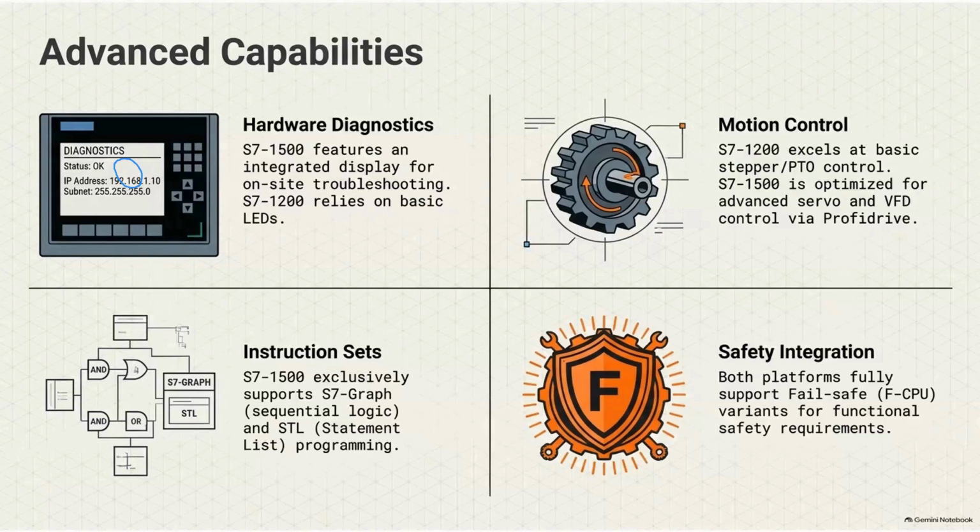So what they do is they look for the n number of times it has opened for n number of seconds, and it assumes, so if the door is kept in open condition for about 10 seconds, the temperature drop is this 30 degrees or whatever. So this is the data that I have collected from the equipment. So in case in future, if someone opens the door, to maintain the temperature, the output should be adequate to maintain the temperature. So this is what advanced controllers are doing now.